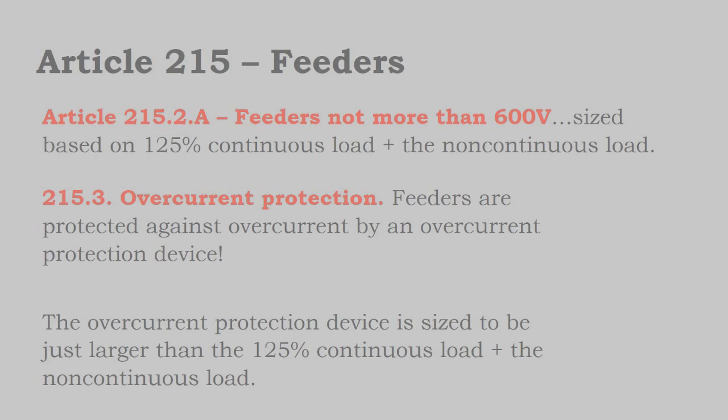You might say, well, why would I want a one-time use fuse rather than a breaker? And the answer is, well, cost. It's not going to happen. If it does happen, you want to know why it happened anyway before you really operate it again. A fuse may be perfect for the job, although breakers may be more simple. It also might cost more.